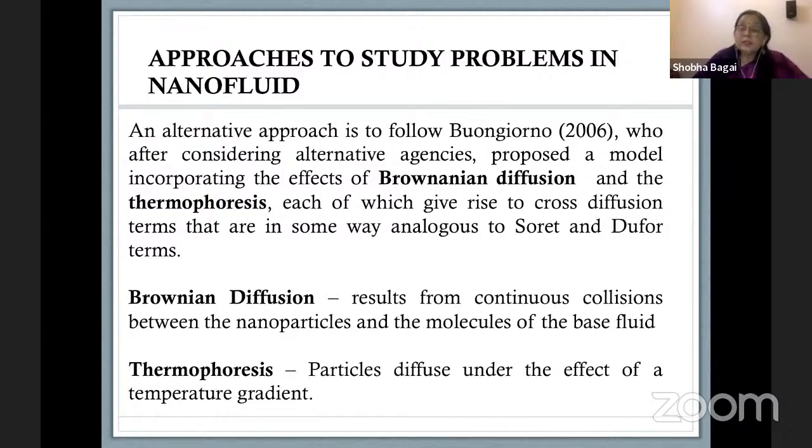The thermophoresis basically is that the heat is transferred either because of a gradient in temperature, or a gradient in concentration. So now, because you also have the particles over here, naturally the heat transfer rate and the mass transfer rate will in fact be affected both by the temperature gradient and the concentration gradient. And those are your Soret and the Dufour effects.